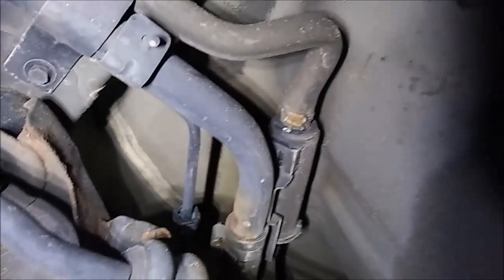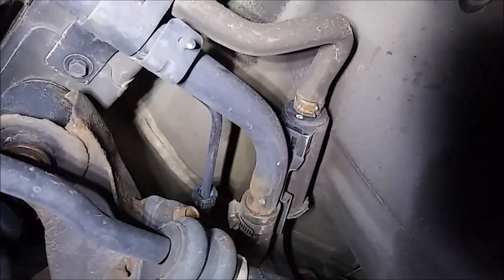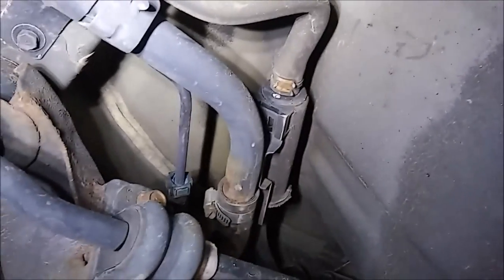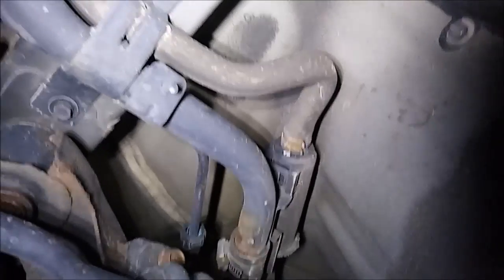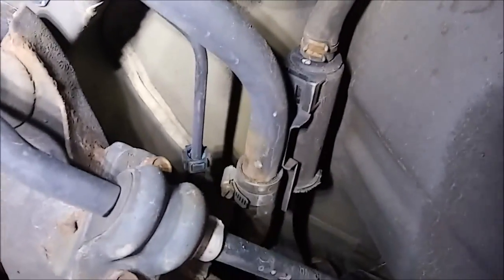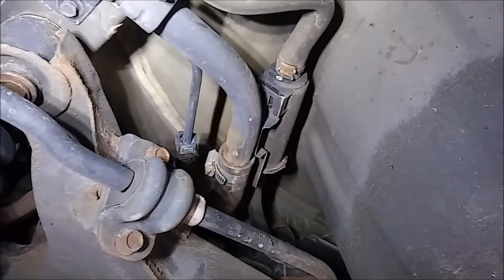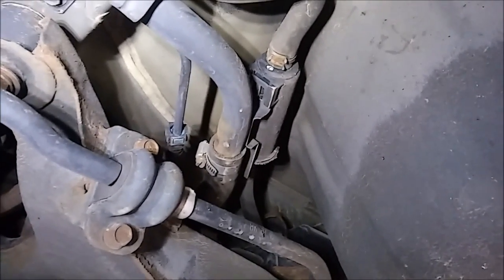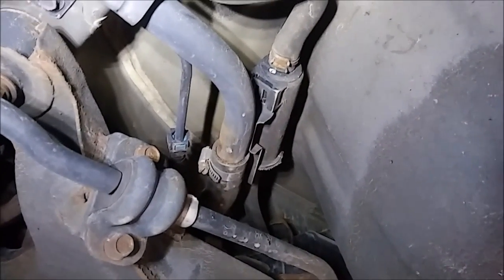hood. Some things to think about: if everything looks good when we do this test up there, and we have this hose going to this vent valve sealed off at the time, what that really suggests is a vent valve problem, because we have taken that out of the EVAP system. I don't see a whole lot of issues with these Hyundais regarding EVAP problems, so I'm not sure if the vent valve on this particular vehicle is a high failure component or not, but we'll have a little bit more direction once we execute this test.